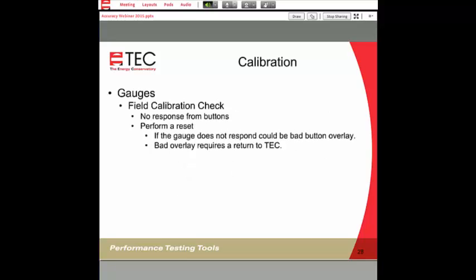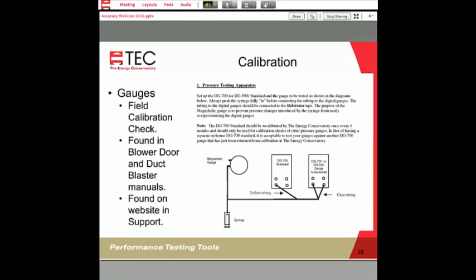Now, there's times where you've done a reset, but you get no response from the buttons. Chances are that means that the overlay might be bad, and that you'll need to return that to the Energy Conservatory for repair. Now, here is the diagram of doing a calibration check out in the field.